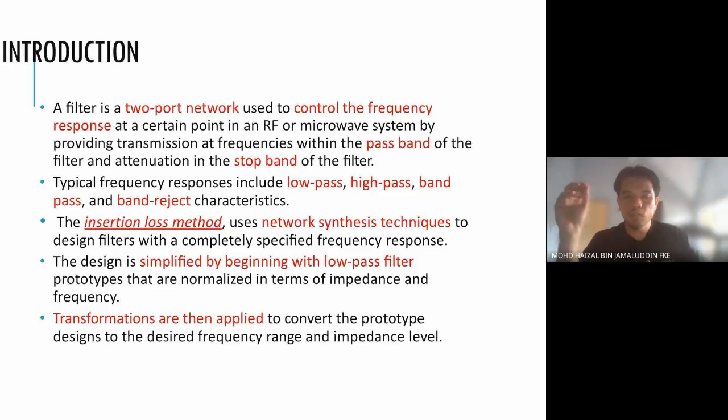The insertion loss method actually uses the network synthesis technique to design a filter with a completely specified frequency response. So we design using the insertion loss method, basically using a prototype low pass filter, or normalized prototype of low pass filter, especially in terms of impedance and frequency. And then we can transform it to the real value of impedance and real value of frequency, or maybe change from low pass filter to band pass filter, band stop filter, and so on.